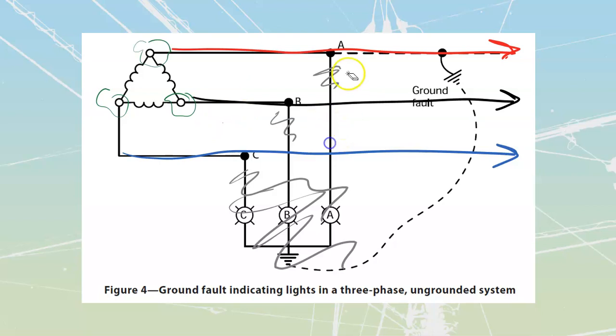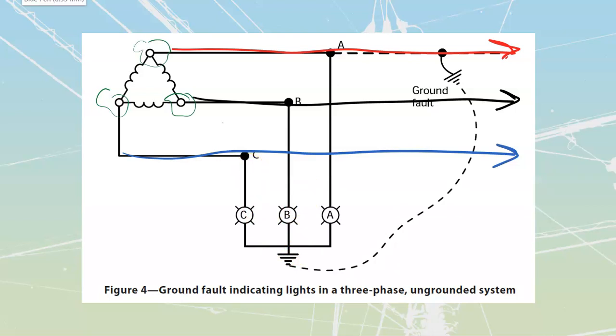And the way that we do that is through these lights over here. If you take a look, these lights are all connected together in a Y type of formation. So if I were to look at these lights, I could actually redraw them in the very center of here, as if that were grounded down.